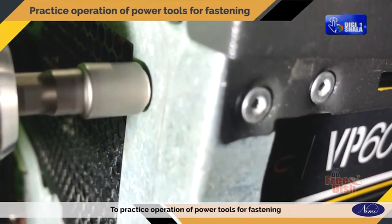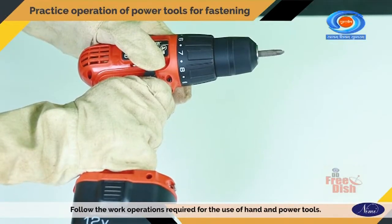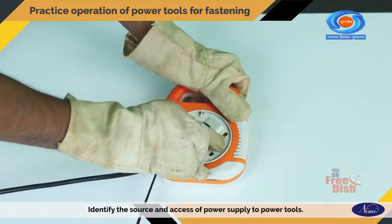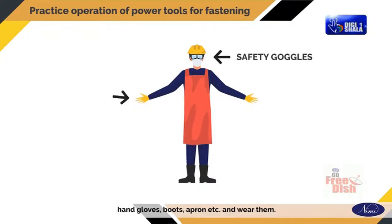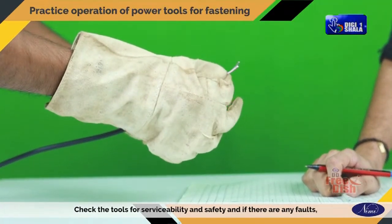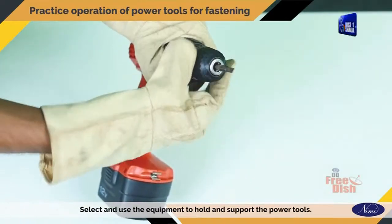To practice operation of power tools for fastening, identify the power tools, follow the work operations required for the use of hand and power tools, identify the source and access of power supply to power tools, select the proper safety equipment such as safety goggles, hand gloves, boots, apron, etc. and wear them. Check the tools for serviceability and safety, and if there are any faults, report the same to the concerned authority. Select and use the equipment to hold and support the power tools.